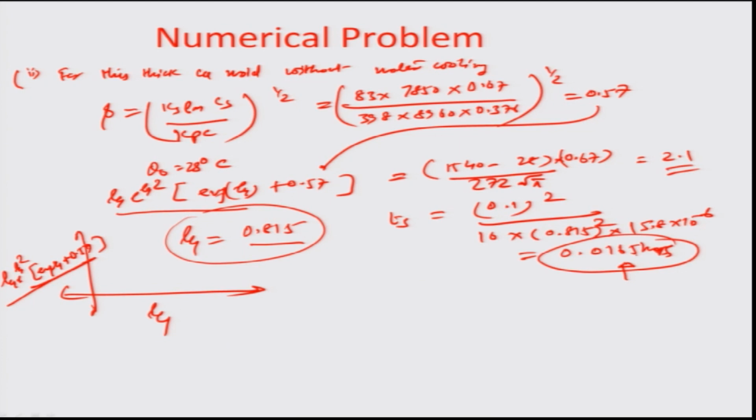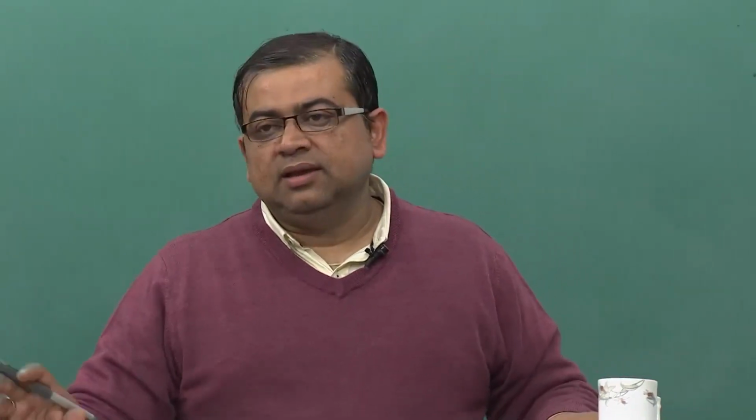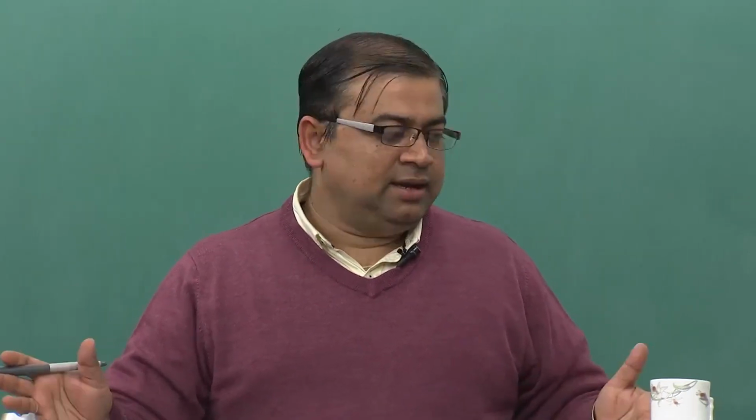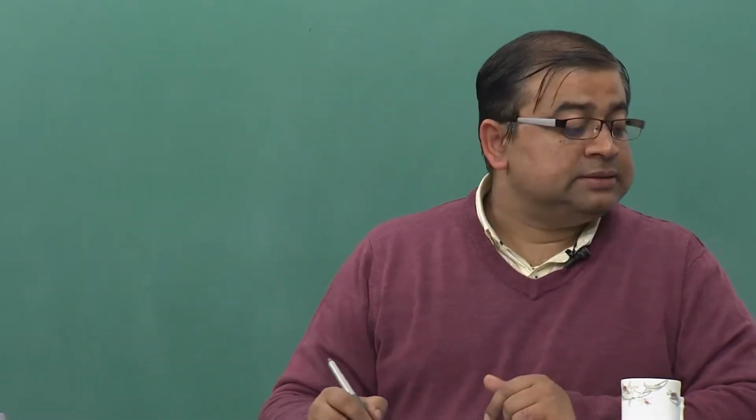So therefore the resistance of the heat flow increases here, and it needs more time for the temperature to come to the freezing point, and therefore the time of solidification in this case is more in comparison to the other case where the mold acts like a heat sink, and there is a constant casting surface temperature because of that. So the surface temperature of the metal theta C